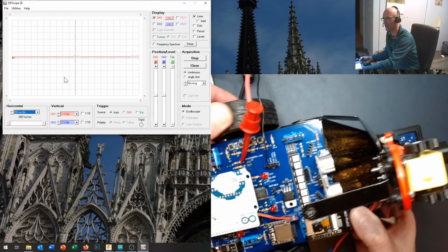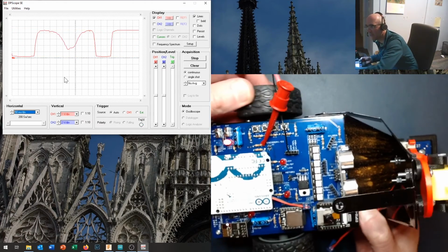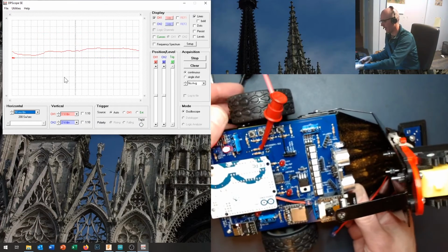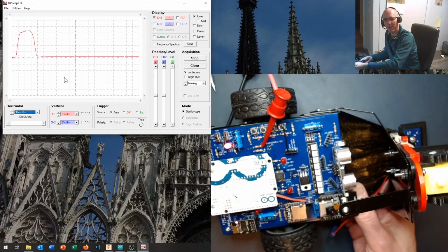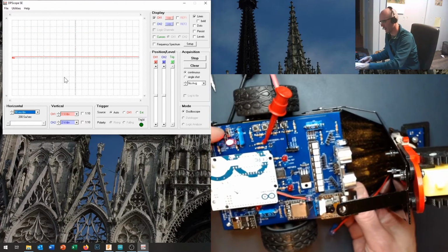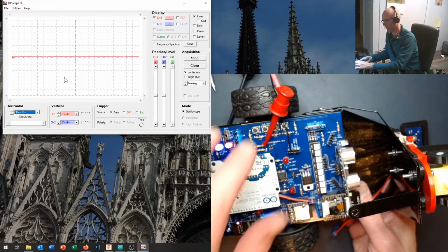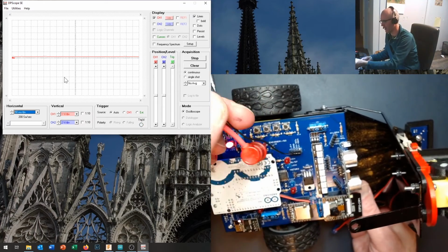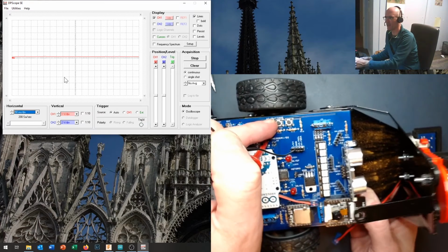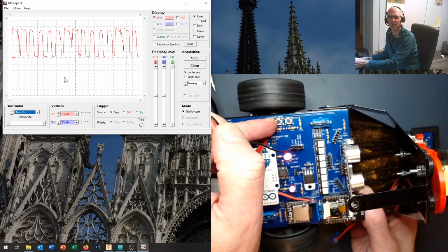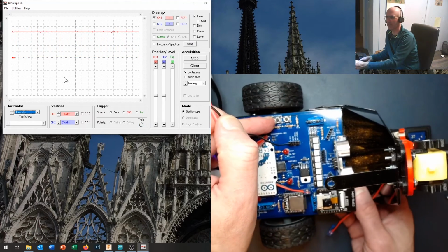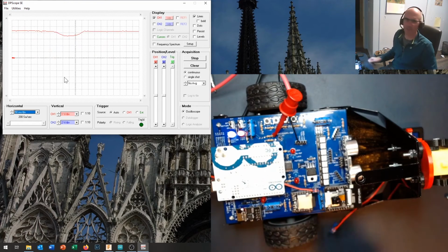Now, spin the wheel manually, listen to it carefully, make sure nothing's rubbing on there. And if you're doing that, then you might see that the pattern's not working quite as well this time out. I'm going to turn on some power right here, and I want to see what that looks like when that wheel's running. Make sure my wires aren't touching the wheel and that I'm holding this up off the desk so it doesn't try and drive onto the floor. Press a button, start the wheel, and there you can see a pattern, and it had a whole bunch of little spikes and noise in there.